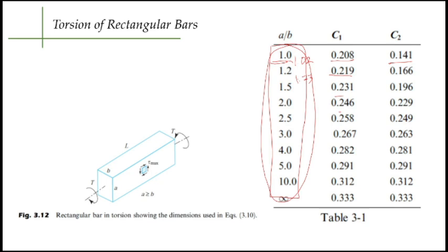Okay, the next, you have also other formulas that you have to remember for torsion of thin wall tubes, wherein a new concept was introduced, which is shear flow. Shear flow, q, is equal to tau t, and q is also equal to T over 2 A naught, where A naught is the cross-sectional area enclosed by the median line.